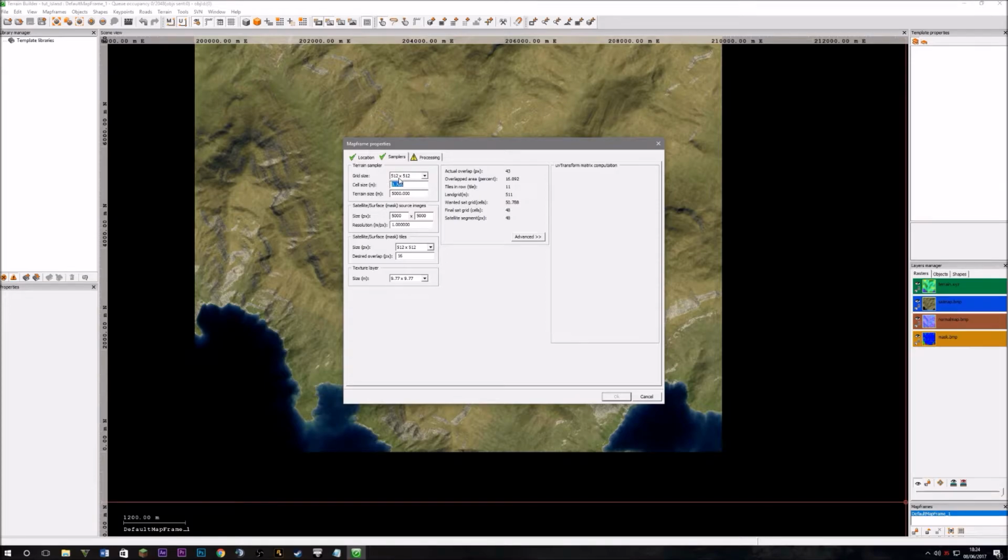I'm going to set the terrain resolution. Actually, grid size doesn't matter, just make sure this is on 1, because you don't want it to be a strange number. The terrain size is 1024.0. The size of your surface masks and all of this stuff, that's 1024.0. And set this back to 40, and that should be that.